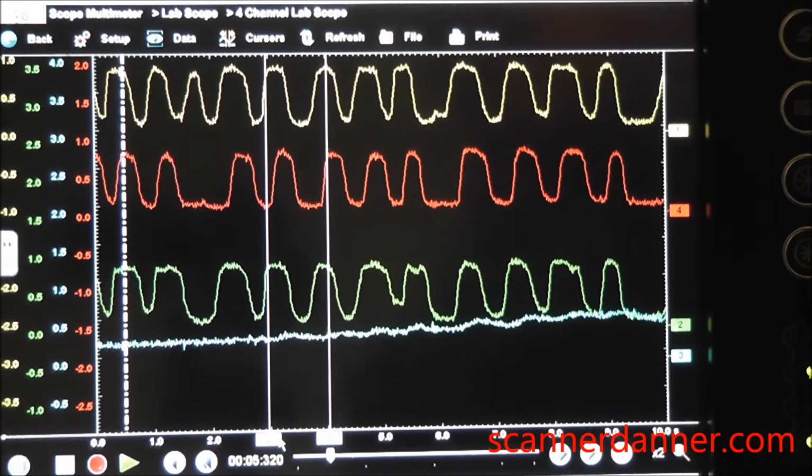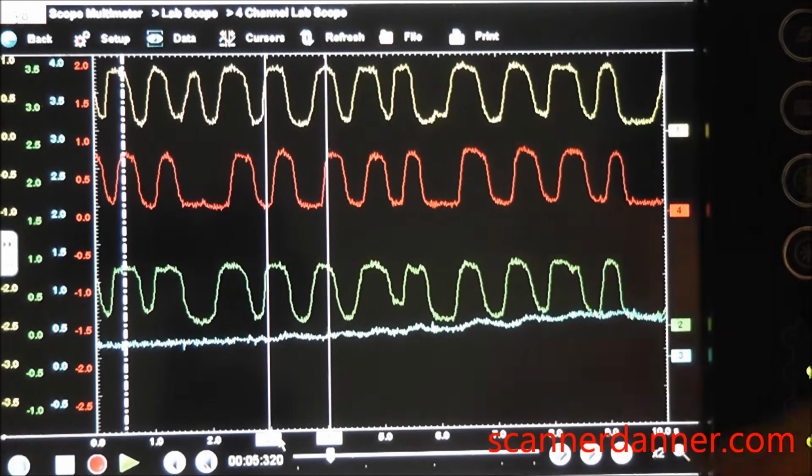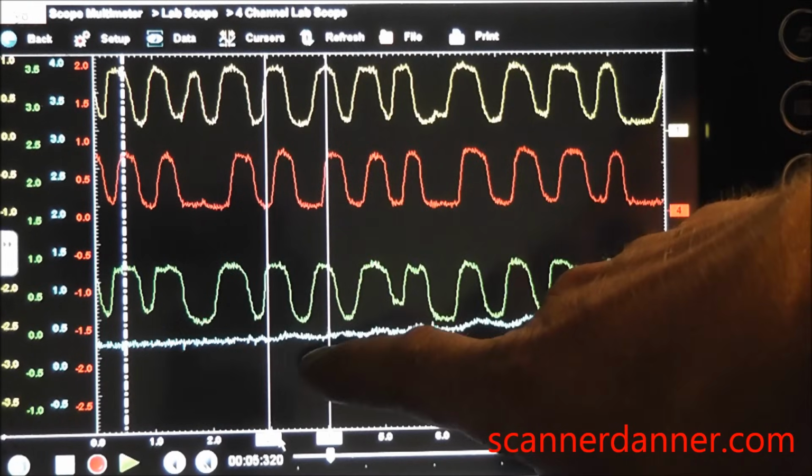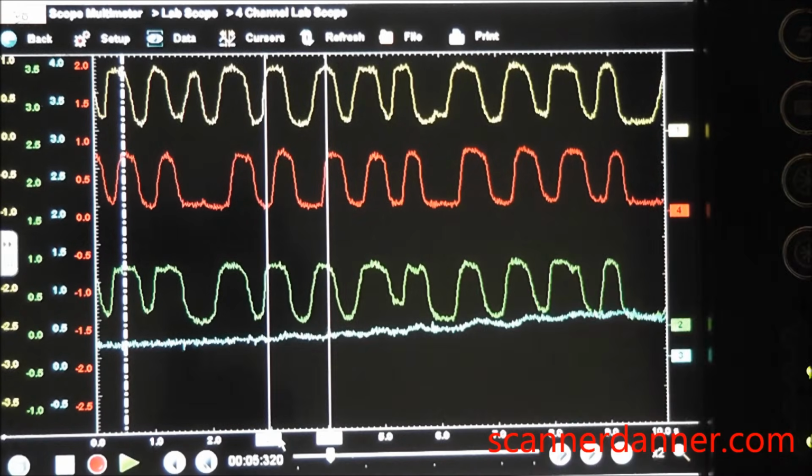But so, there's some other checks. Look at the frequency of your O2s. You want to make sure your downstreams respond too, and that's easy on this one. This cat's totally dead, but on one like this down here that's not moving much, you can flood it with fuel just by fluttering the pedal and watch the reaction of the downstream sensor and make sure you're good there.